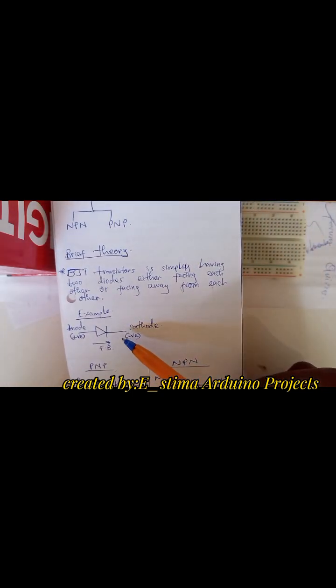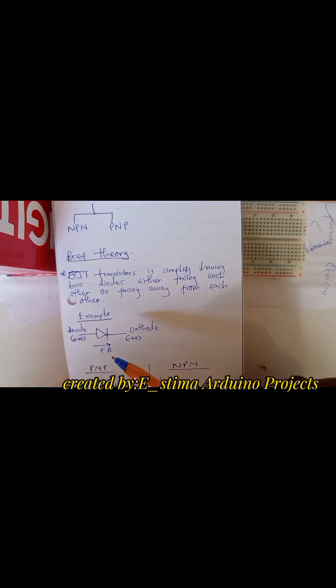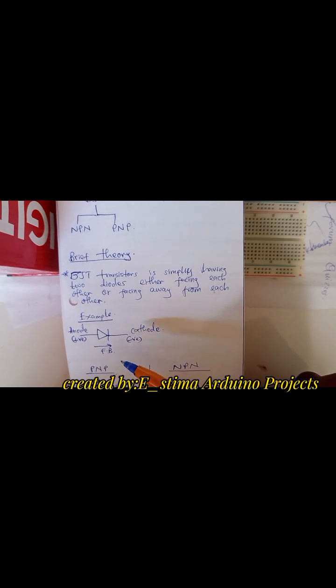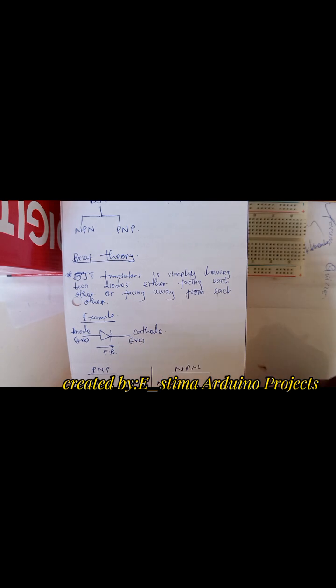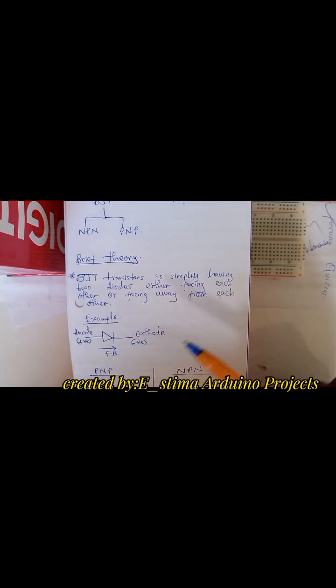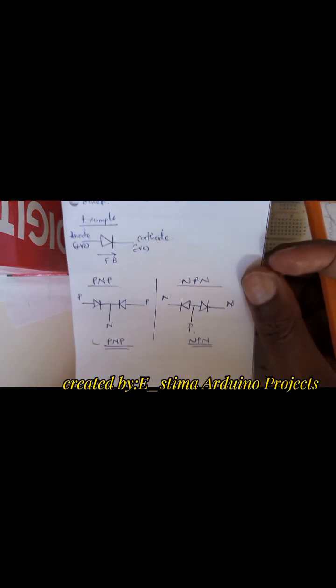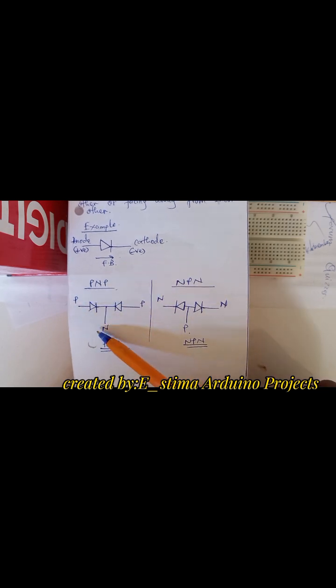This is a simple diagram of a diode. A diode simply is a two-terminal semiconductor device that allows current to pass through it only in one direction. And when it allows current to pass through, the diode is said to be forward biased. So this is my anode, which is made of P-type semiconductor, and this is my cathode, which is made of N-type semiconductor.